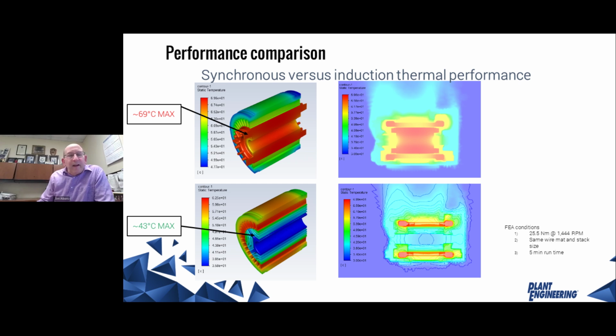The last thing that I wanted to cover, and just one last advantage of a synchronous motor, is that it has a little bit more maintenance and reliability capability. One of the reasons is because the rotor doesn't get hot. This shows you an induction motor on top and a synchronous motor on the bottom. They're actually the exact same electrical design. One is running with an induction rotor and one with a synchronous rotor. And you can see the heating difference here between the two.